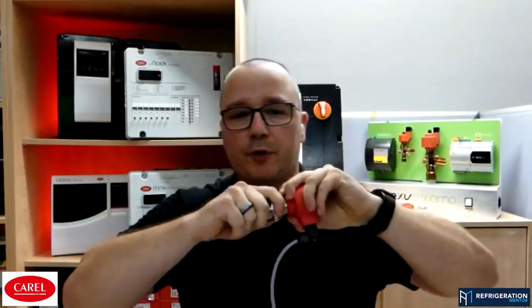So the installer was changing the components, was working the first time with this kind of application, and he was not really sure what is going on. Why is the valve opening to 19%? And why is it opening more and going back to 19%, why is he filling up the application with refrigerant? And he was not sure, is the valve working or not? And he removed the red hat from the body just to see, is this working? And what happens if I put it back? He was thinking about a magnet valve. And he expected to hear something like a closing and opening of the valve.